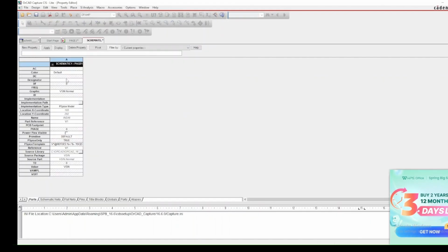And then for the voltage source we have VAC here. We are going to give a value of 10. So it's basically the AC voltage that you are giving. AC value, I'm going to give it 10. And then basically you're not going to go for DC here, so you're going to give it a 0.